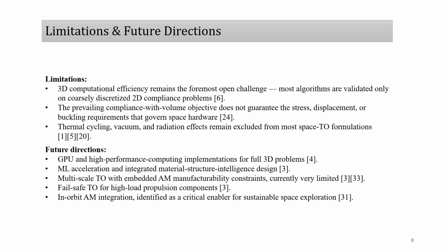Second, the common compliance with volume formulation is not enough for space hardware. Real components must satisfy stress, displacement, buckling, vibration, fatigue, and qualification requirements. Third, environmental effects such as thermocycling, vacuum, and radiation are still rarely included in the optimization formulation.